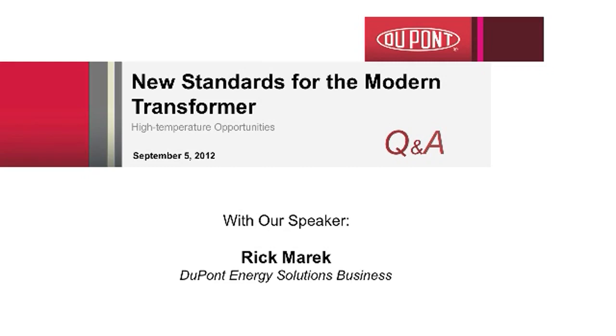I'm assuming that the reference is to the enamel, and enamel in the different liquids can be an issue at elevated temperatures. So we have to be careful there, because many of the enamels are not suitable for high temperature application in liquid-filled transformers.